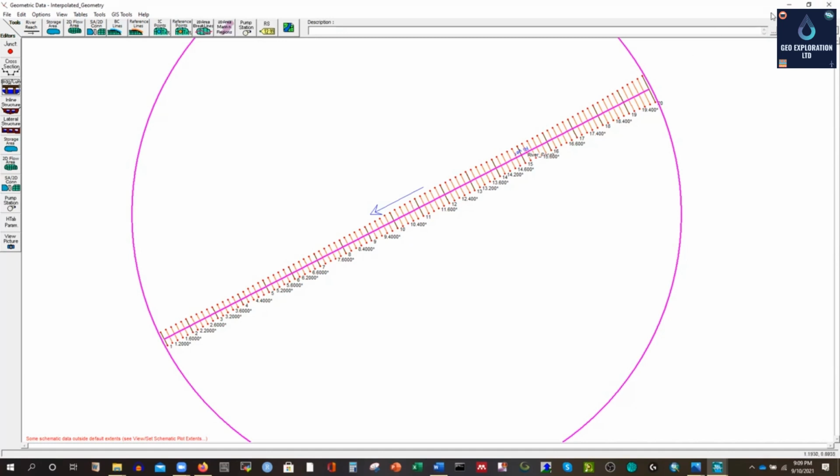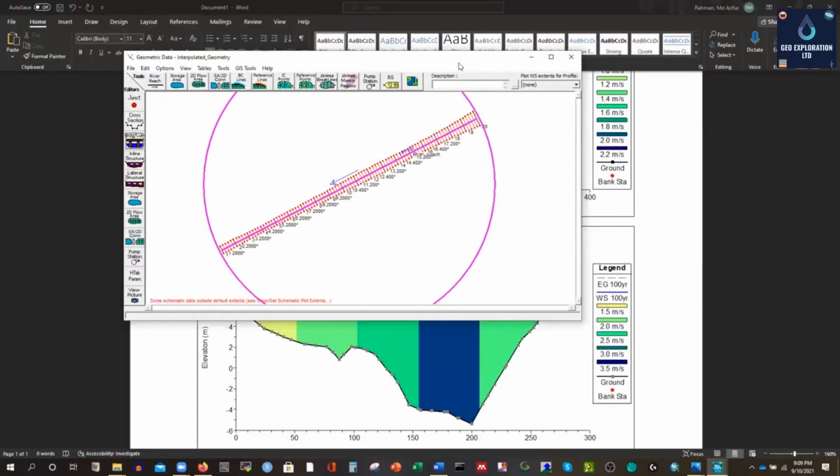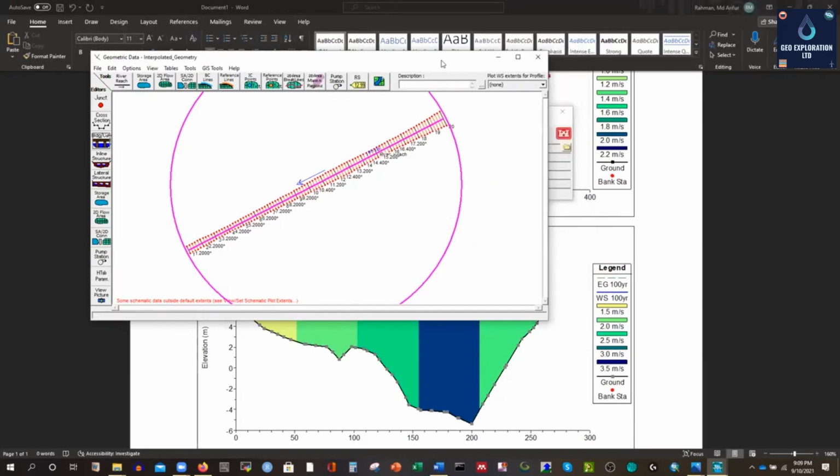And what will the scouring be? There will be different types of scouring. From the bridge, it is called pier scour from the bridge piers, and there will be scour from the abutment of the bridge, and there will be some local scour as well. So we'll combine them and add them up, and then we'll calculate the total scour, and based on that scour, if it's necessary, we'll have to provide some piling while constructing this bridge. So that's the idea. We have to be able to calculate everything.